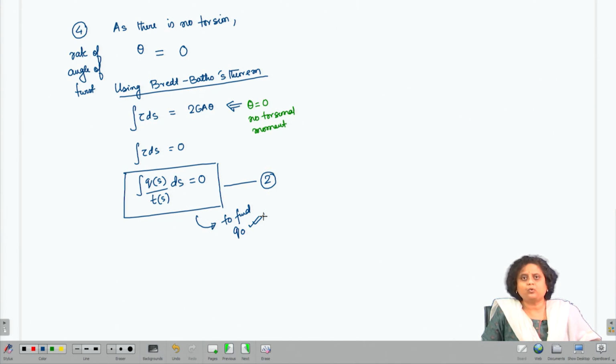What will happen if the shear forces are not passing through the shear center? It will not pose much of an issue, because if the shear forces do not pass through the shear center, we can always make up an equivalent force system where the shear forces will pass through the shear center and there would be an additional torsional moment about the shear center.